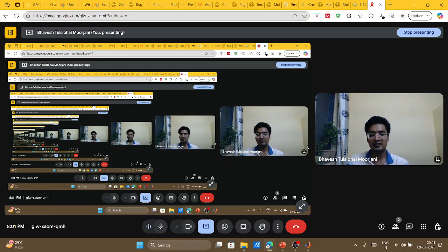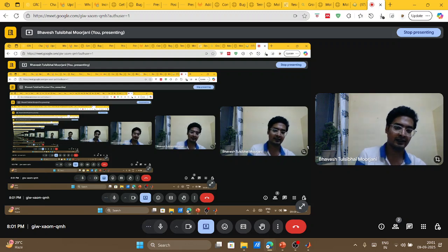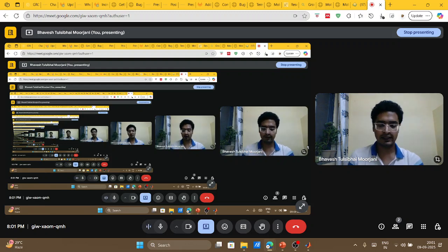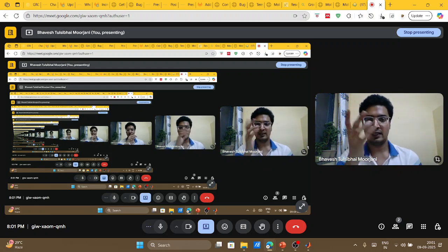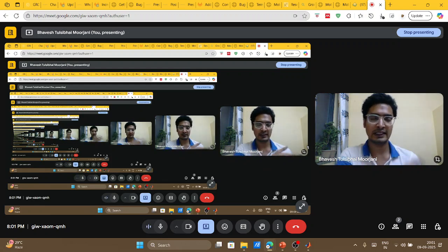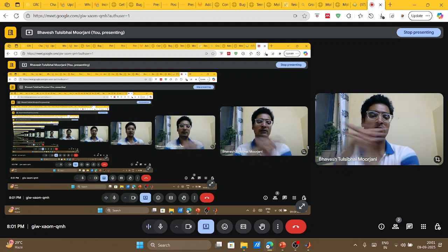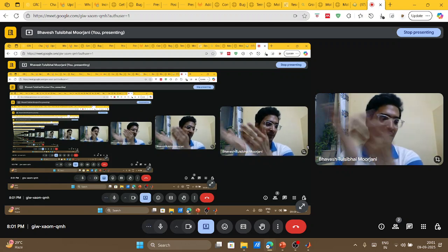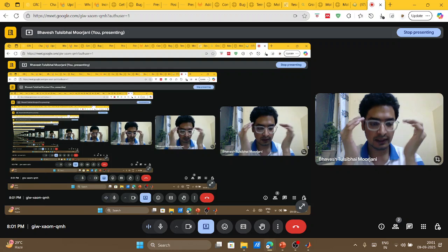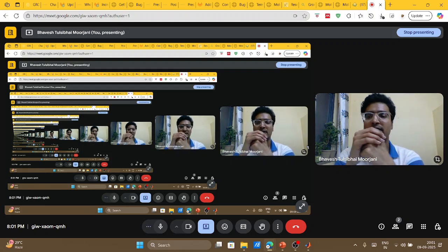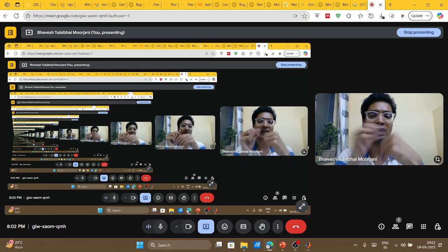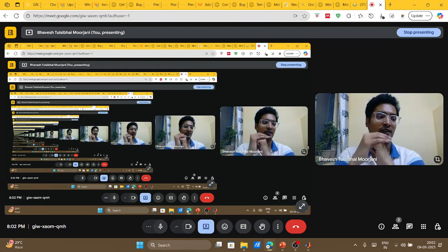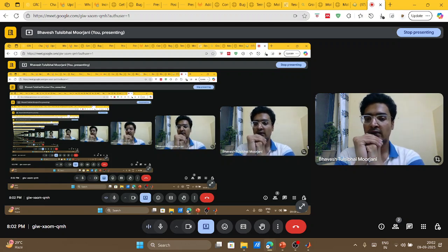Now the question I want you to ponder is this: since it's a co-current heat exchanger problem, we solved it very easily. We converted it into ordinary differential equations with respect to Z, the change in temperature with respect to Z. We knew the initial values, and we solved it through our ODE solvers, initial value problem solvers, right? But what will happen if instead of co-current we have a counter-current heat exchanger? Can you think about what will happen?